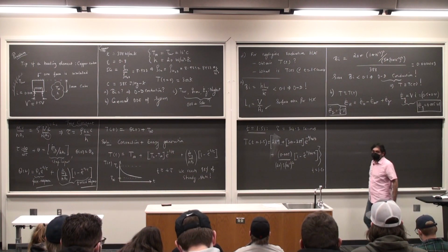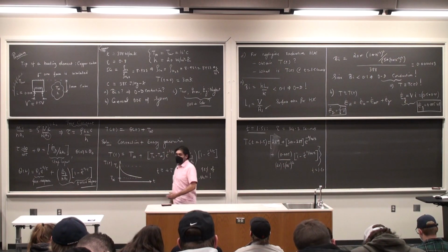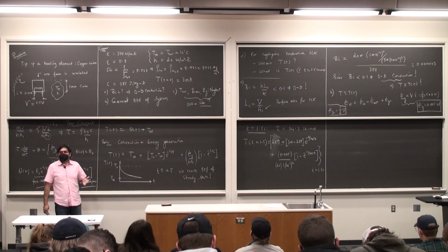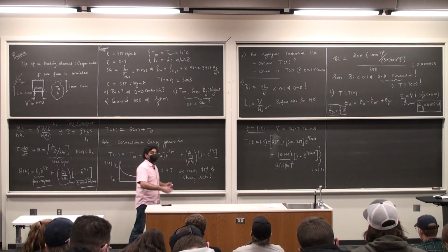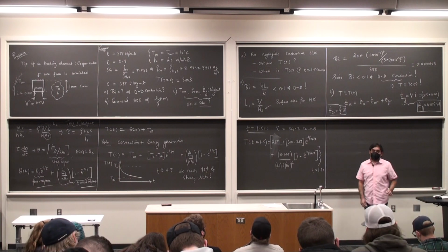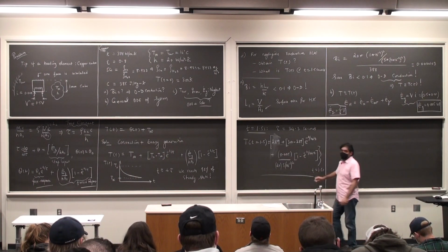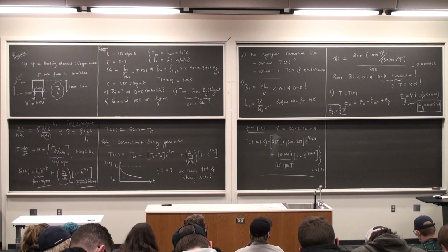Would the temperature have changed by any much of a value? Probably not a whole lot, because tau is 34.3 seconds. So at 1.5 seconds, I'm not even sitting at a fraction of tau. Okay, so the temperature is approximately going to be the same as your initial temperature. Not much of a change. Okay. I don't have the final numbers, but I'll post the numbers on your course page. Okay.